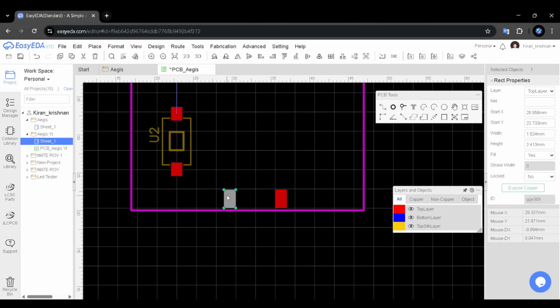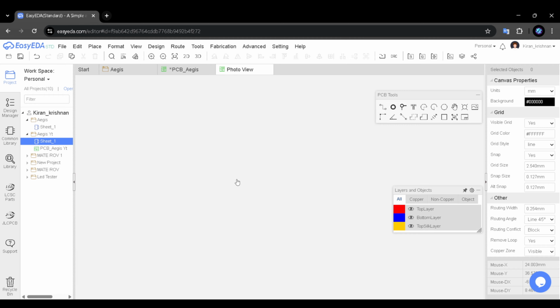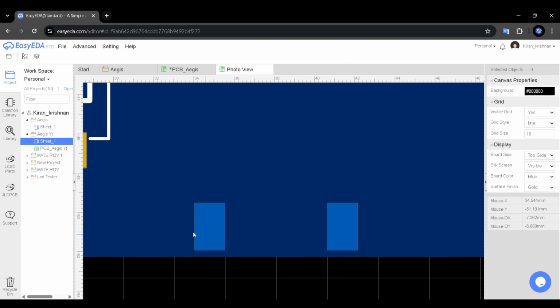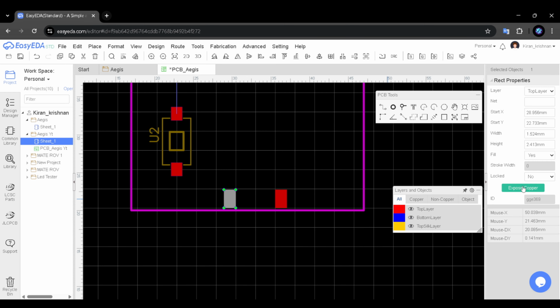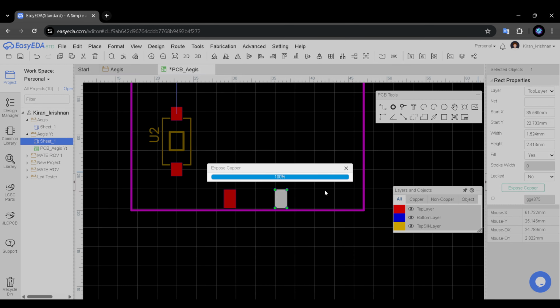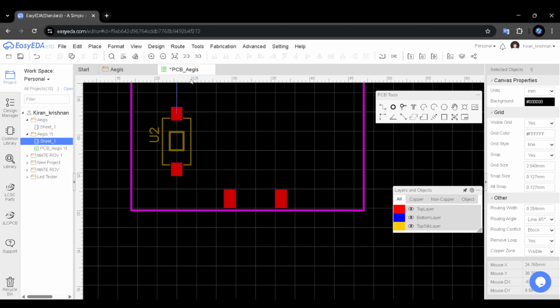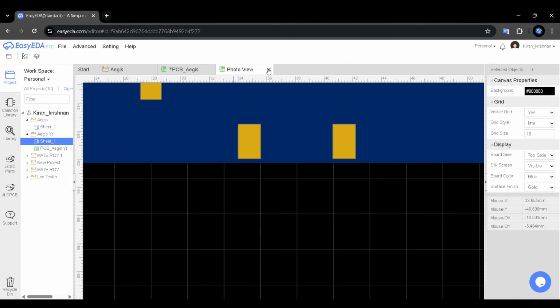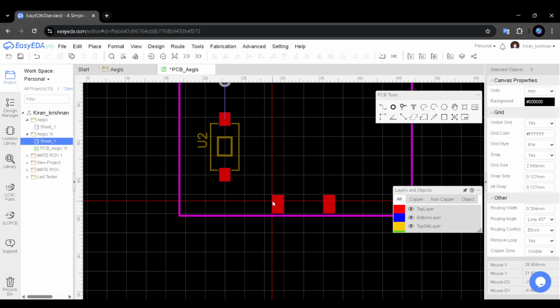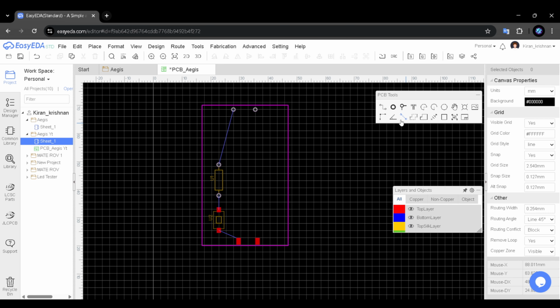Okay, now what most people forget is that right now it's inside the particular PCB. So you gotta expose the copper. Only then you can access it from outside, like you can solder onto it from outside. So right now, see, now you can see the copper part. So right now we gotta connect this. Oh, wait, I gotta draw a rat line from here to here. And the final rat line from here to here. So this is basically what it does.